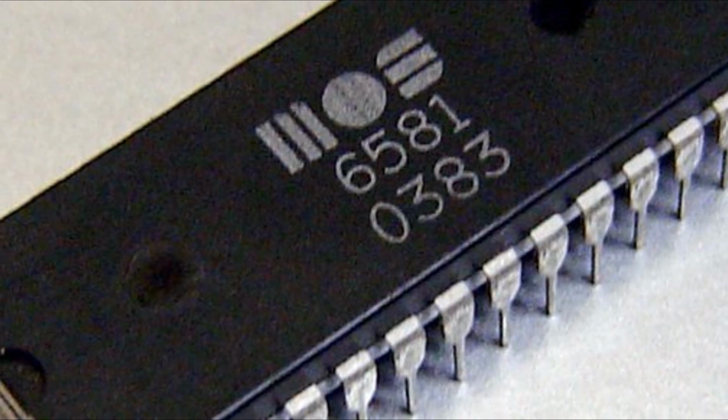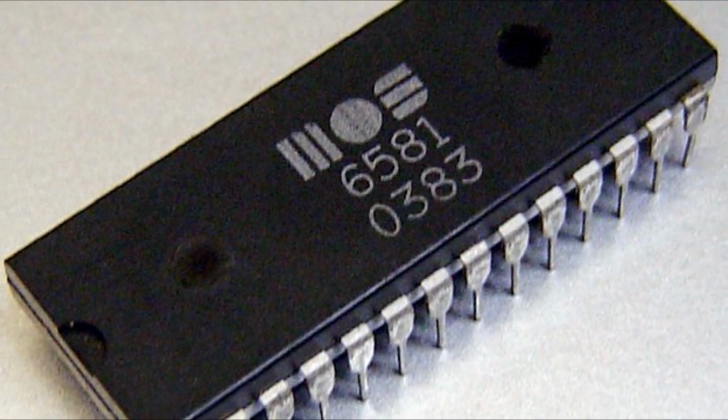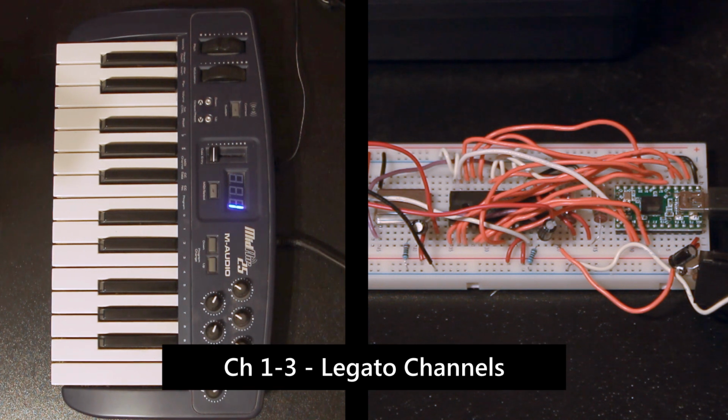The 6581 SID chip would theoretically work, but instead of using a 9-volt secondary power supply, you'd need to use 12 volts. When you plug it in, it makes a little hello world sound and should show up as a MIDI plug-and-play device on your computer. It's also programmed to blink the LED on the Teensy every time it receives a MIDI note on, continuous controller, or pitch bend message.